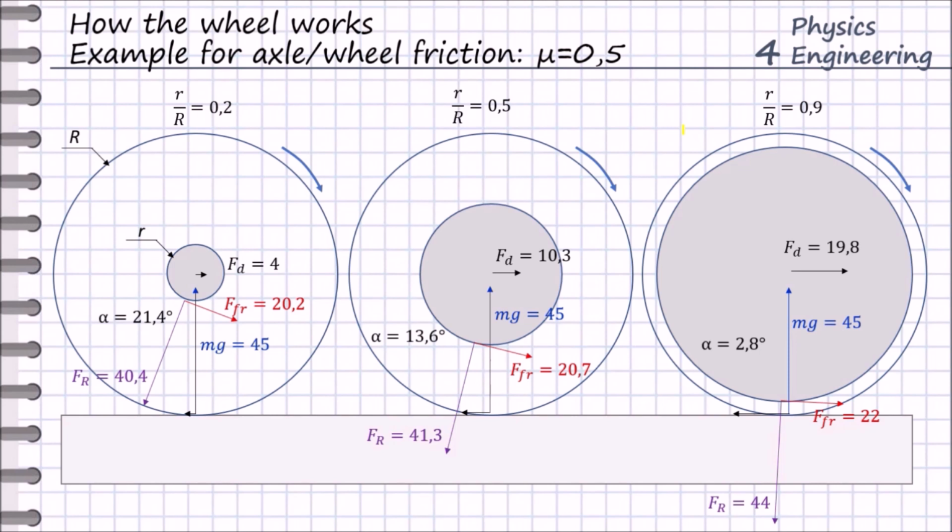So why does a different shaft diameter make a different resistance to the motion? Why does a smaller shaft diameter make the resistance to the motion smaller? The explanation is the following. System equilibrium for the torques requires that, for example, if we calculate the torque around the contact between the shaft and wheel, then we have 2 torques only: the torque from this reaction force, this blue arrow, and the torque from the stiction force.